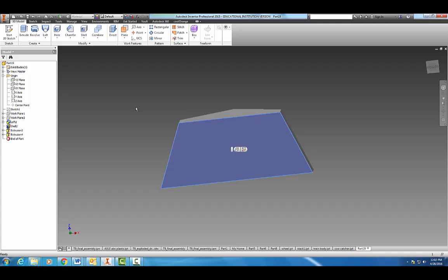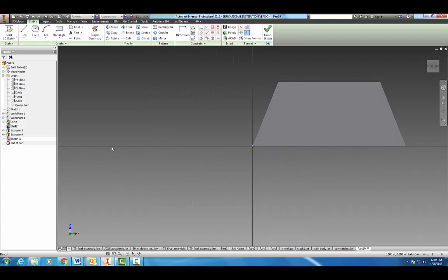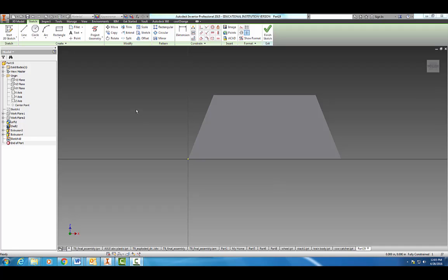So go ahead and click on this face and start a 2D sketch there. So let's come up to our circle tool. I want to place the circles in their general locations here, and they have a diameter of 0.125. Put our other one over here, 0.125, and I'll put this one, trying to get them away from those hidden lines here, 0.125.